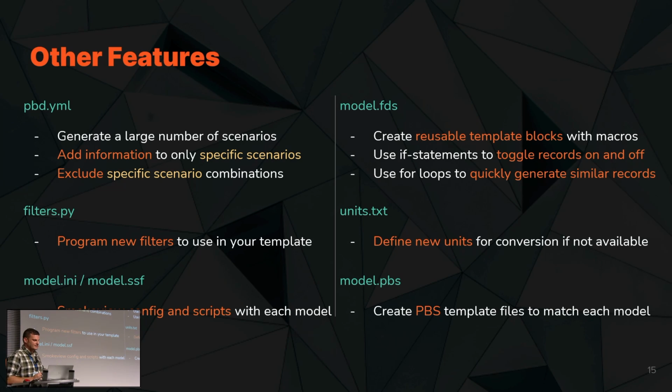Turning on and off slices is actually in the SSF. So there's a lot of configuration that you can tell SmokeView in the ini file about what to do when it opens. The model.ssf will allow you to script the output from SmokeView. So you can tell it, these are my floor elevations, I want to get the visibility across the floor and get those all pretty quick.